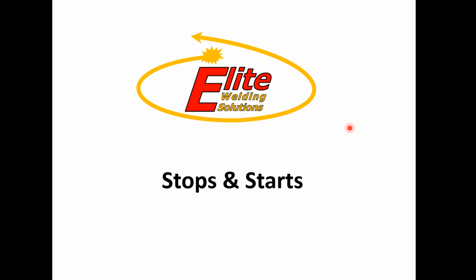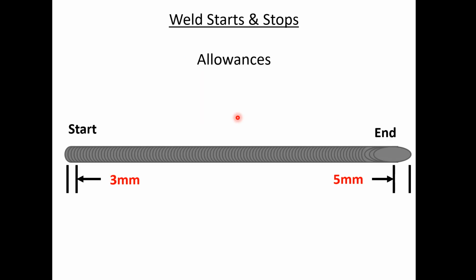Thank you. Stops and starts. Not much to be said for stops and starts other than the start of the weld doesn't get tested for a few millimeters, and the end of the weld, which we know as the crater, which I'm going to talk about a little bit more here, is also not part of the inspected areas. And when I say inspected areas, I mean areas that go to quality and actually get cut into pieces to make sure you have a good sample. The start of the weld could be a little bit discrepant. The end of the weld could be very discrepant. There's only something special about the end of the weld that we need to discuss a little further.